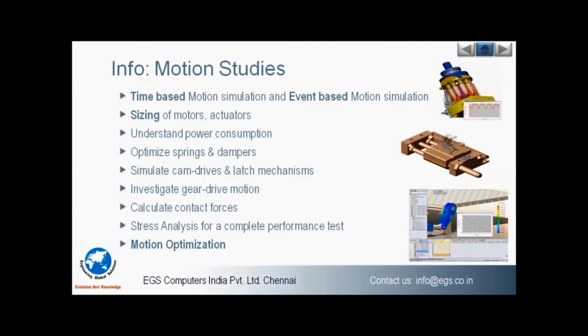And for mechanism-driven options, as I was talking about the event-based motion, we can directly simulate the cam drives and the latch mechanisms. A simple example is the door operation, which uses the hinge mate, and we can investigate the gear driving motion. By all these aspects, we are going to calculate the contact forces and the stresses. The user also has the option to directly import all the kinematic loads to the static study to directly study the stress analysis for the performance.